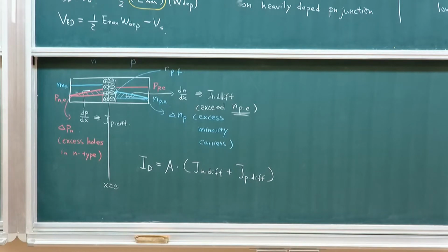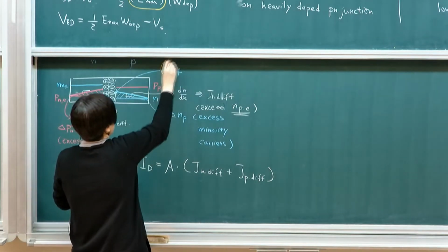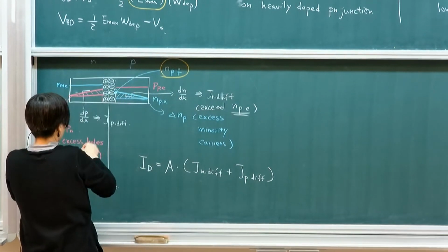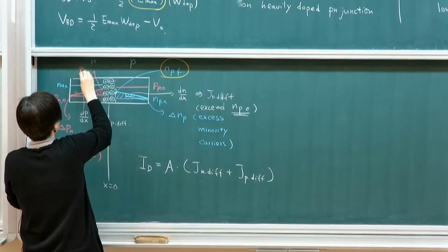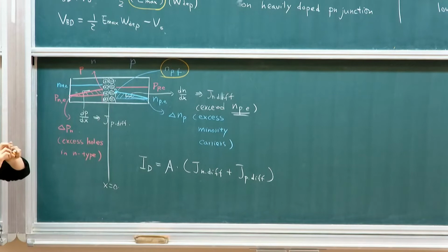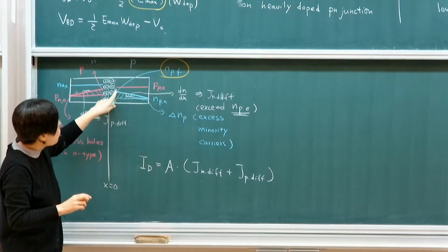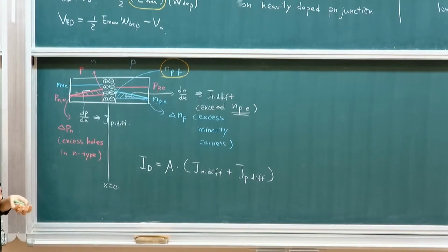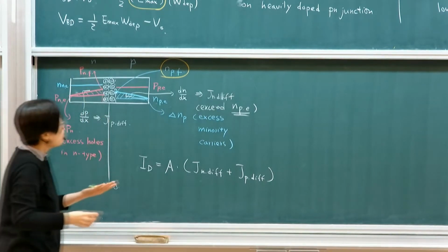So in this analysis, what is the key parameter you need to know? We want to know this. What governs the dn/dx will be the level that's being raised at the border. That would limit how far or how fast it can diffuse. The difference between these two would give us how much excess minority carrier is actually in the other side, and that would cause our current level. So that would be the minority carrier during forward bias. Let me define this.